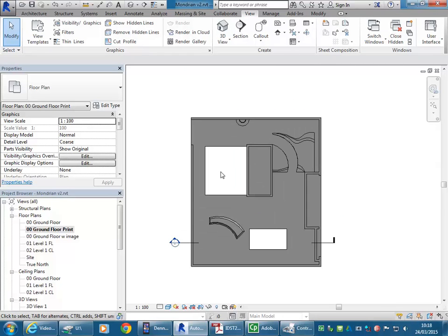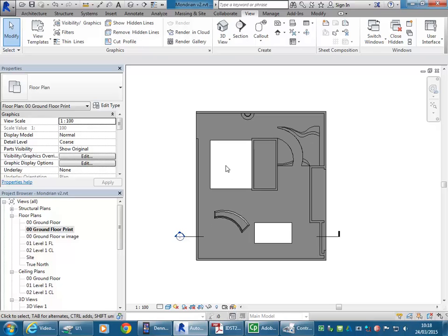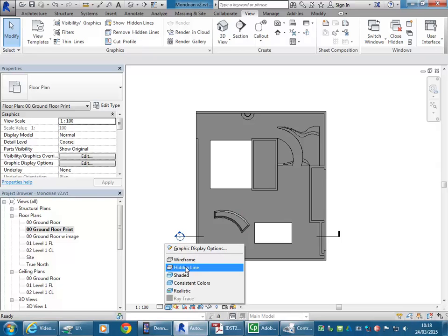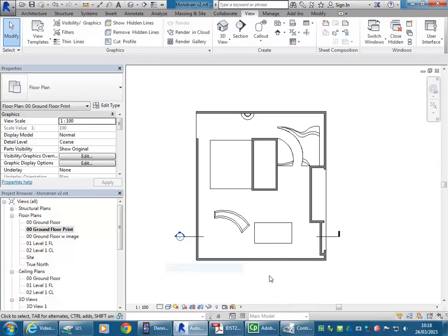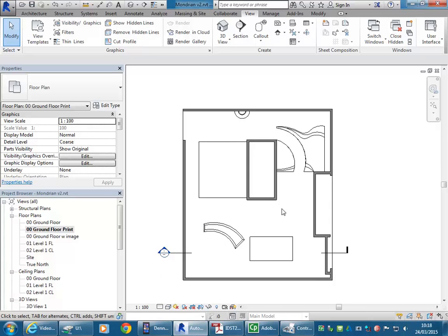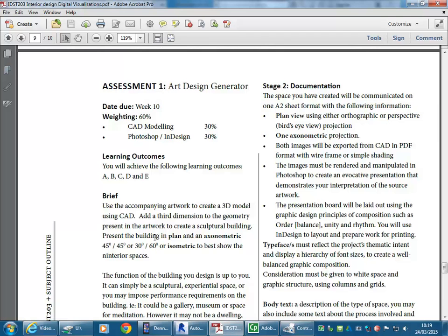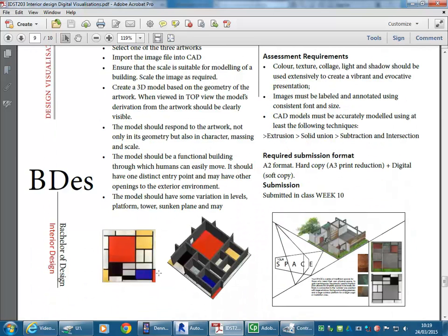in Photoshop, you don't need to have the shading or materials showing in Revit. Revit has a full suite of materials and lots of different options for them, but again, you're doing it in Photoshop, so we'll set this to hidden line to give a clean display. The grey in the walls is actually not too bad, but you might prefer black, which I think is shown here. It's a bit hard to see, but it looks like it's probably black. This one, I think it is.